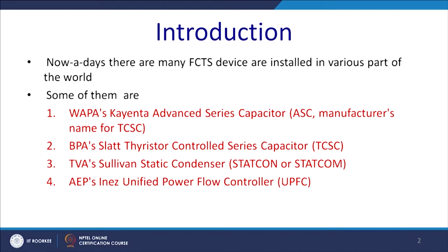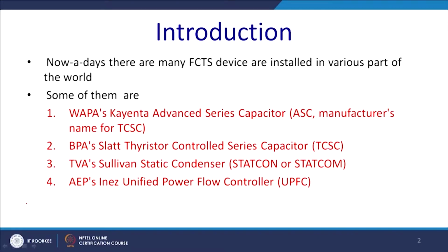So, one is the WAPA advanced series capacitor, as they used to call it, an advanced series capacitor, which is essentially a TCSC. Thereafter, BPA's Slatt thyristor controlled series capacitor, and this is also a TCSC. Thereafter you have TVA, a state-of-the-art synchronous condenser, essentially the STATCOM, first put into operation, and AEP first came out with the unified power flow controller.